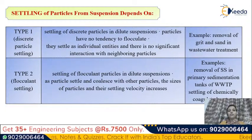For the settling of discrete particles in dilute suspension, the particles have no tendency to flocculate. They settle as individual entities and there is no significant interaction with neighboring particles. That means all these particles act in their individual nature. And for flocculent particles, in dilute suspension, as particles settle they collide with other particles, that means they get attached to other particles, and the size of the particles and their settling velocities increase.